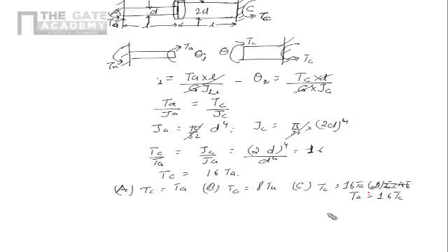Now obviously again we can apply the elimination thing here. Both the shafts have equal length, they have the same material, but they have different diameters, so obviously they cannot carry the same torque. This is wrong. So option A is outrightly eliminated. And because the lower diameter shaft will obviously be carrying lower torque, TA cannot be more than TC.